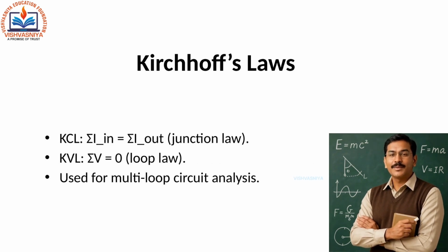In complex circuits, we use Kirchhoff's laws to analyze current and voltage. Kirchhoff's current law, also known as KCL, says the sum of currents entering a junction equals the sum of currents leaving it. Sigma I in is equal to sigma I out.